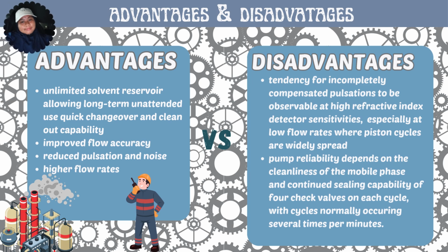Moreover, since each head has two check valves, pump reliability depends on the cleanliness of the mobile phase and continuous sealing capability of 4 check valves on each cycle, with cycles normally occurring several times per minute.